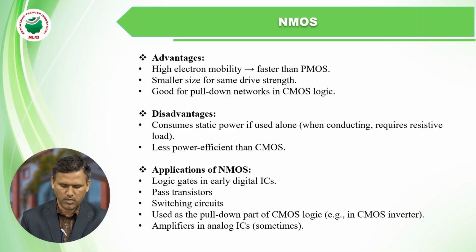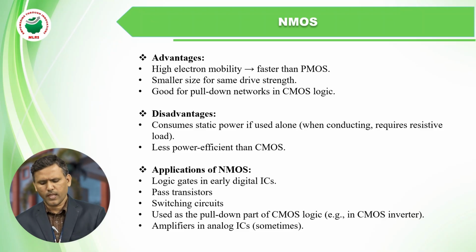Applications of NMOS are logic gates in early digital ICs, pass transistors, switching circuits, use as the pull down in CMOS logic, and amplifiers in analog ICs.